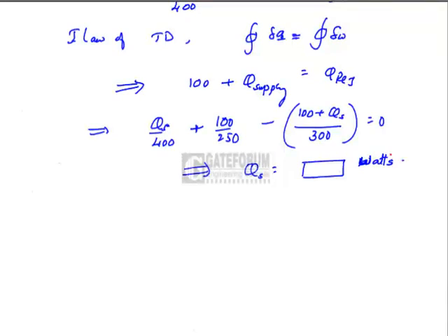This is the answer to the problem. Here the assumption is the cycle should be reversible because he has specifically mentioned in the problem the minimum amount of heat required. Minimum means COP should be maximum. For COP to be maximum, the cycle must be reversible or Carnot.